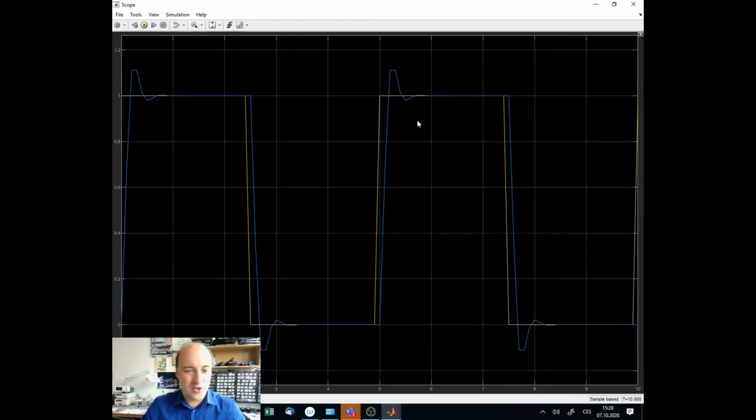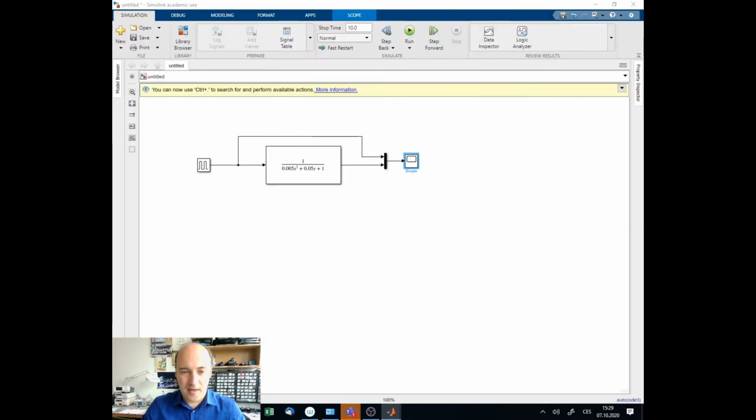So I have very few points in my data. So this is telling me that actually the sampling time needs to be much smaller than the speed of the system. And if you look here on this system, it's not a time constant, we don't call it that in second order systems, but this smallest number is telling me something about how fast the system is.